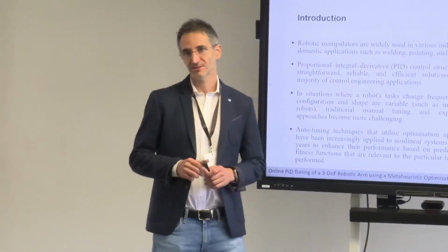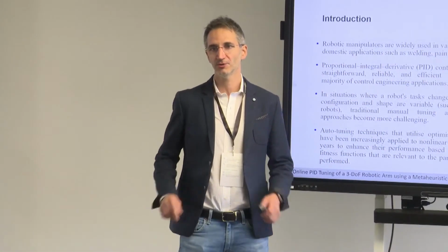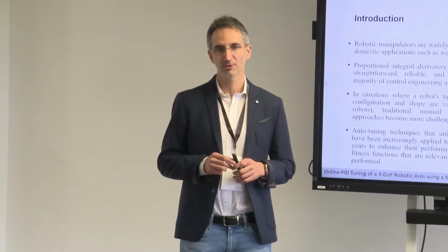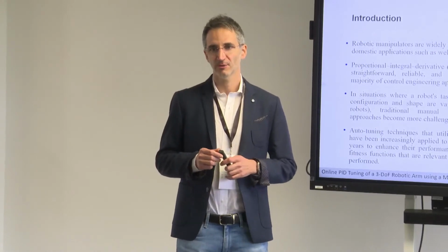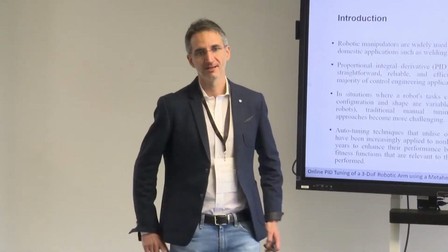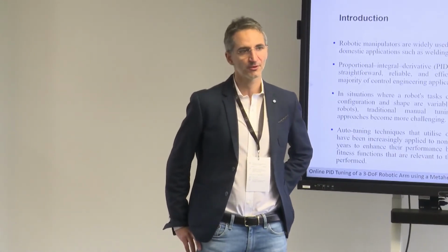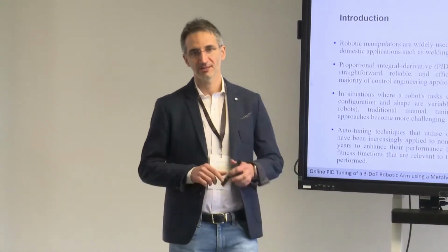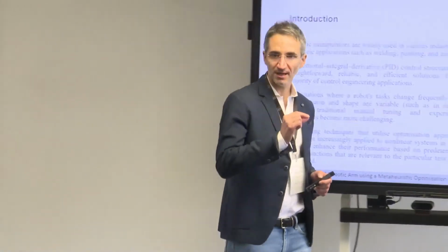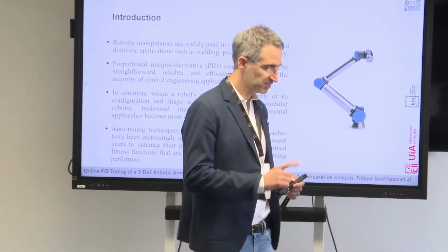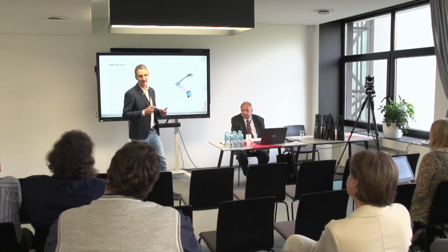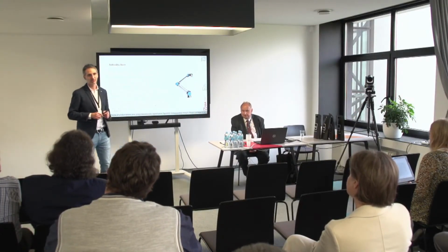Traditionally, in robotics, for 20 plus years, since the beginning of robotics, we use PID controllers, proportional integral derivative controllers, which are really the basic controllers for robotics. Using PID controllers, we can minimize the error iteration after iteration so that the robot can really reach the target, or at least I can minimize my position error.